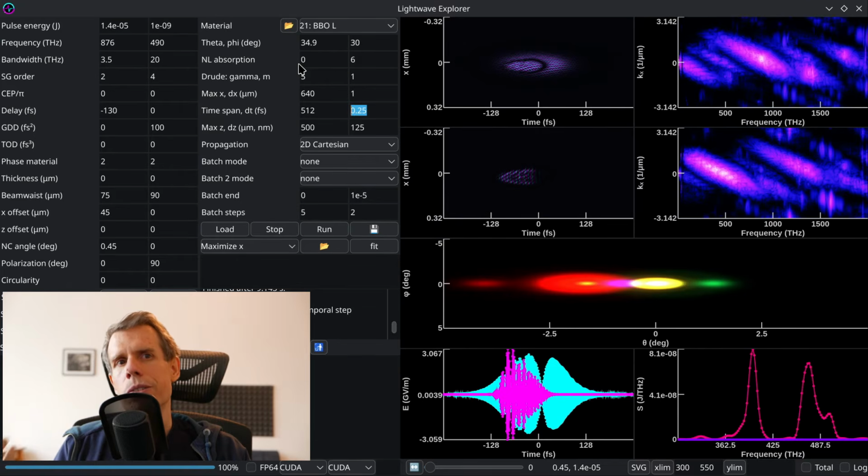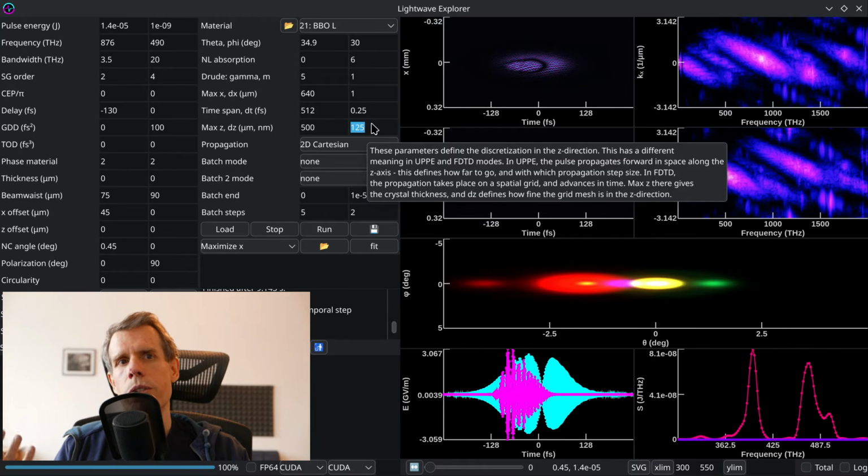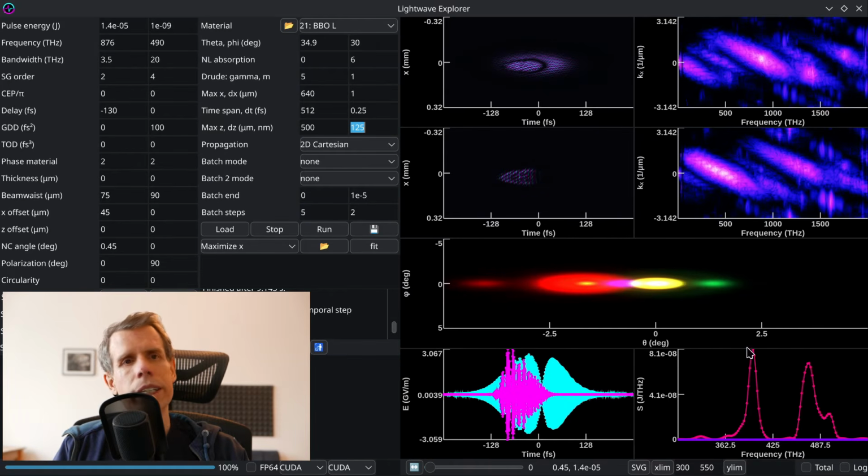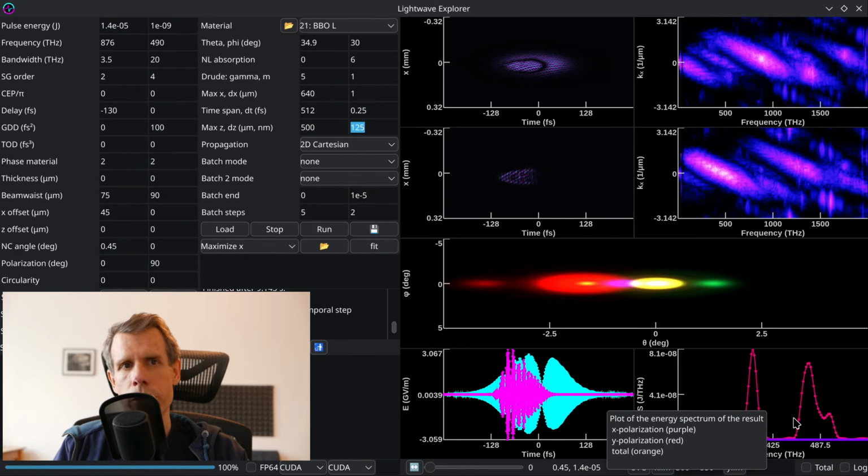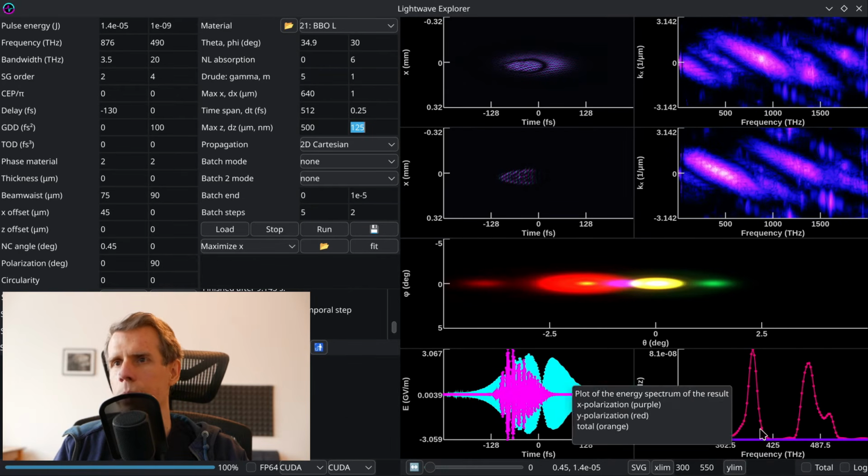Try to exclude high frequencies that aren't valid anyway on this grid. That means make this step size coarser. And if you have good values and it's still not converging, then you make this step size smaller. Eventually you should find a set of parameters where everything is going to work. Make sure you're looking at some relevant observable, such as the spectrum, where you want to measure the spectrum, and then you should be safe.